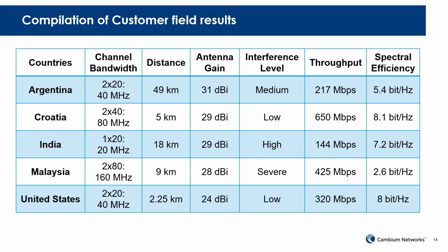What dishes are recommended? The second question I have here. So, generally speaking, we carry the radio wave antenna, so we recommend the radio wave antenna. You can find the part number from the Cambium price list, and all the antennas we carry are dual pole because this is a MIMO thing. So we have both V and H. You should be able to find that. I think we have 2, 3, 4, and 6 foot.